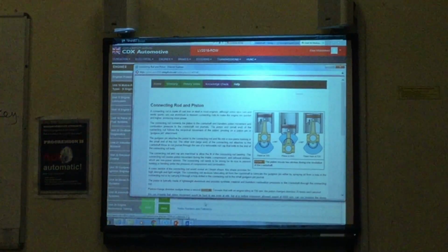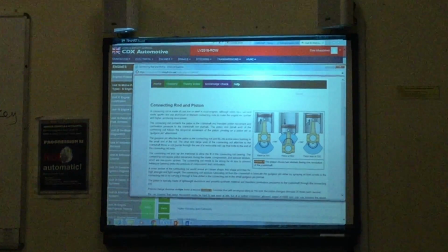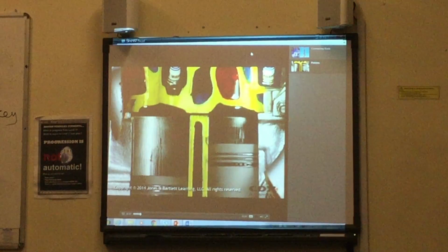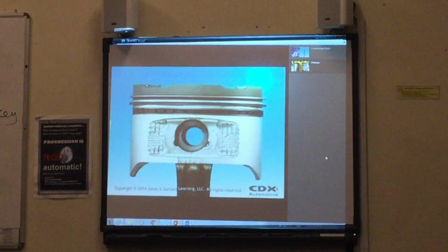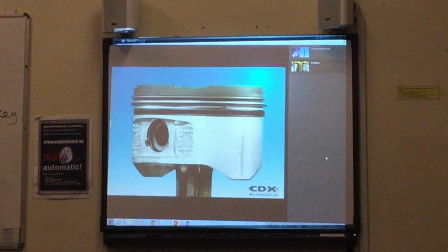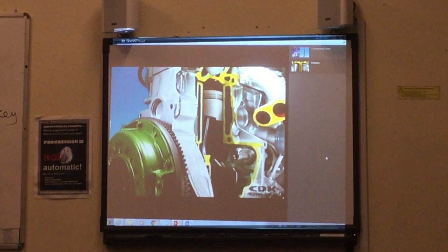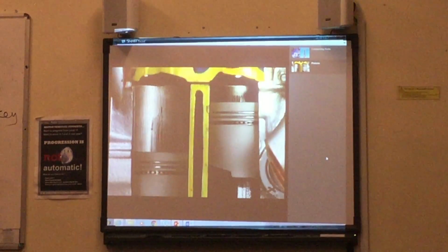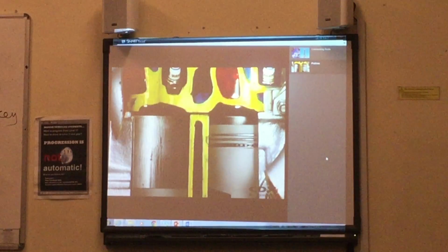Let's start with the piston. The piston, with its connecting rod and bearing, transfers the force of the combustion and expansion of the power stroke to the crankshaft. The piston itself, its rings, and the piston or wrist pin are together called the piston assembly. The cutaway shape on this piston allows it to clear the counterweights on this rotating crankshaft. The shape of the piston crown depends on the shape of its combustion chamber and its compression ratio.